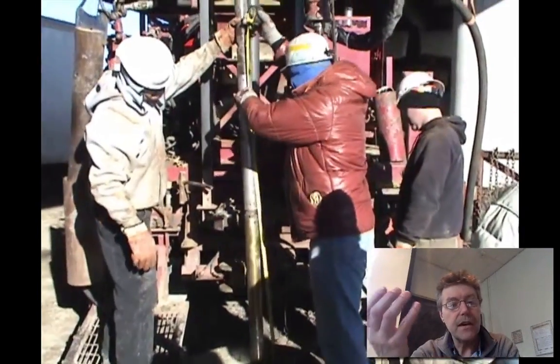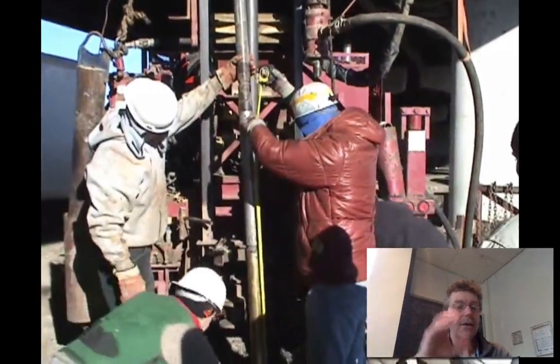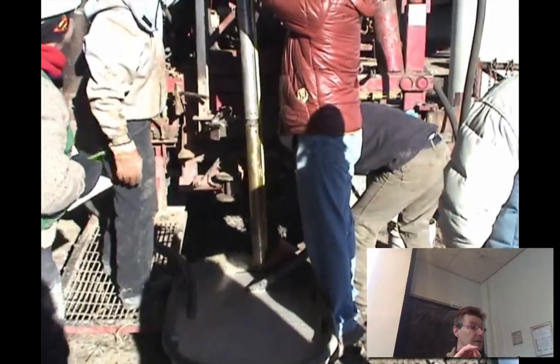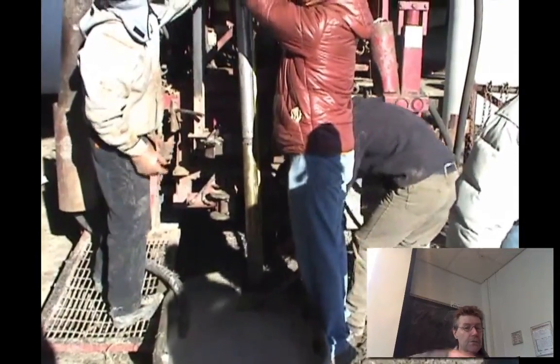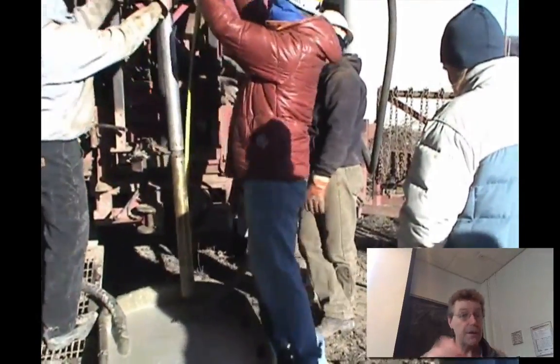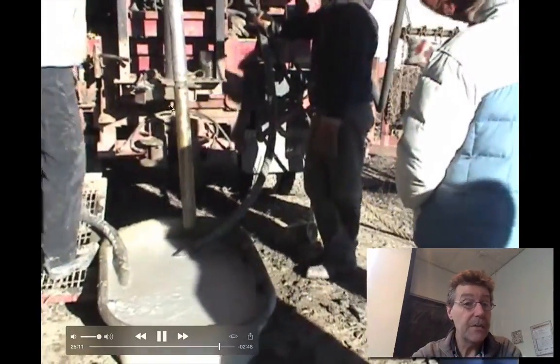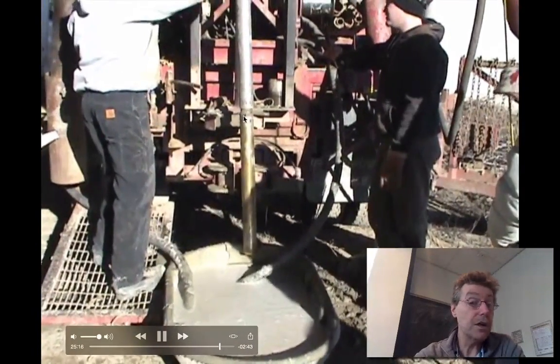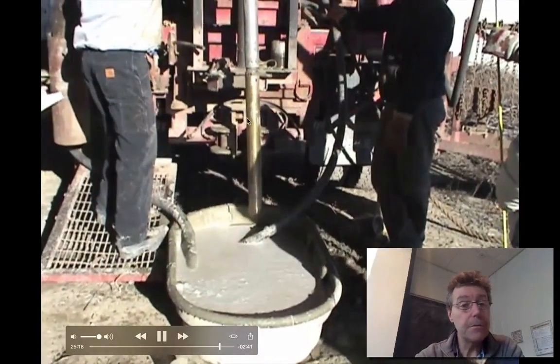And so it doesn't allow any air gap to exist between the bottom of that syringe and the soil. When you withdraw it, you can pull on it to make a vacuum in the airspace at the top of this tube, and therefore you physically suck the sample in and lock it in. So it's a piston sampler that's used for that.